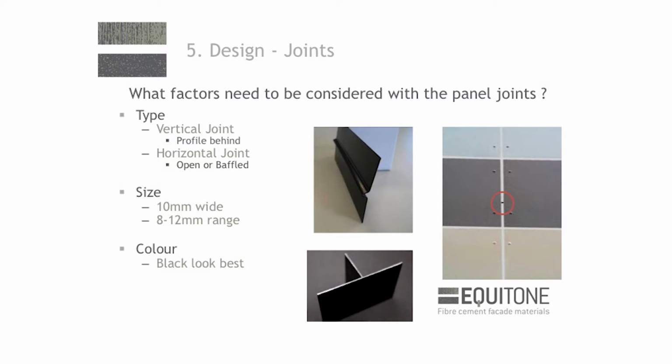What I do not see a need for, for you guys, is to put sealants in the cavity space, in the joints, like the old systems. Because first of all, for you guys, you've got the masking tape up around all the joints. You've then got the backing rod. You've then got to fill them. You've then got to trowel them off. You've then got to remove the masking tape. And if you've left the masking tape on too long, you've then got to come and remove all the adhesive off the masking tape that's still stuck to the panel.